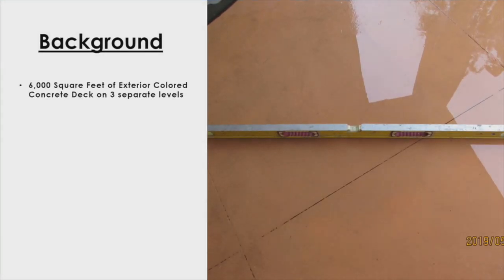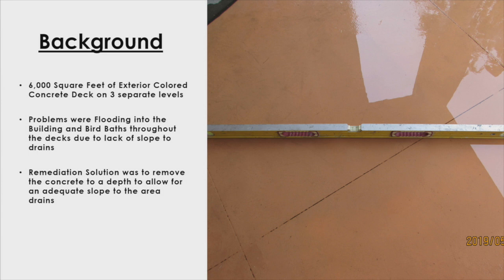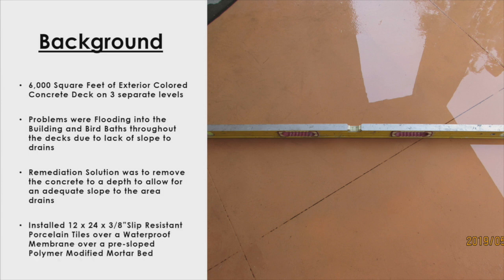So we came up with some ideas on how to deal with it. This was about 6,000 square feet of an exterior colored concrete deck, 3 different levels. Problems were flooding into the building, as I said, and bird baths because there wasn't an adequate slope to the drains. And the remediation was to remove the concrete to a depth to allow us for an adequate slope to the various area drains, which were kind of in an inconsistent location. So it was a real complex challenge having us to figure this out. And this is what I'm going to show you how we did figure it out.